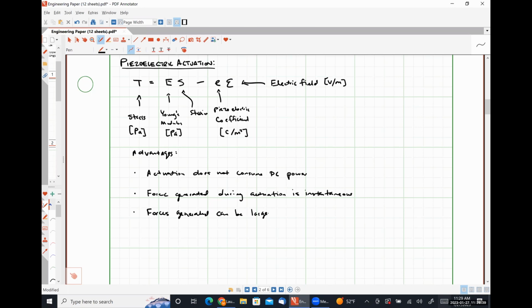As I mentioned the last time we talked about piezoelectricity, it is also part of most of our digital watches and computers, because a quartz crystal resonator is an example of a piezoelectric actuator. We're applying a voltage at a particular frequency to generate mechanical deformation at a particular frequency that is used as a clock reference circuit.